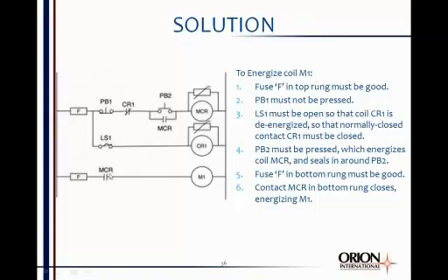It will also close this contact. Now, if this fuse on this bottom rung is good, so that's another condition that must be true, coil M1 will energize. All of that has to be true in order to energize coil M1.